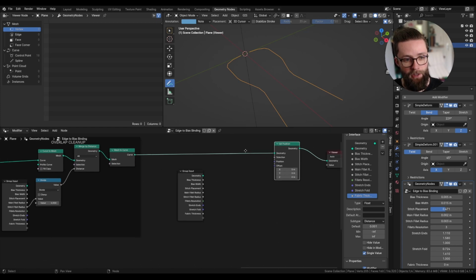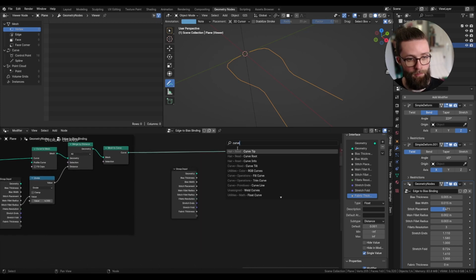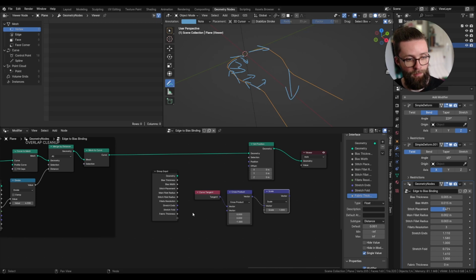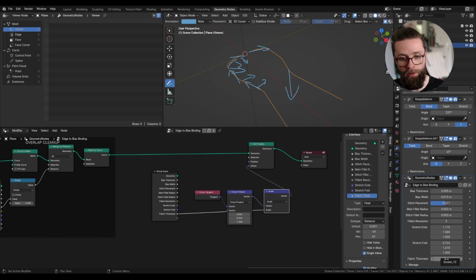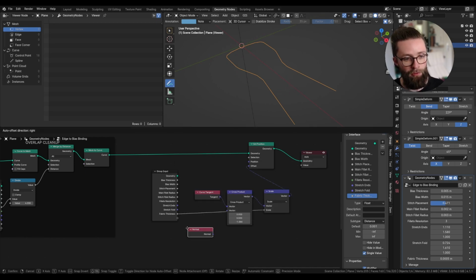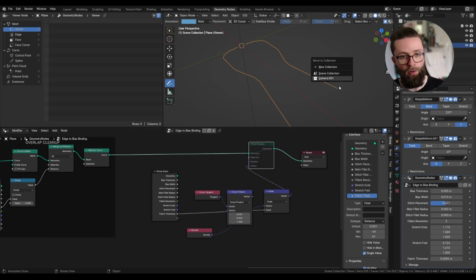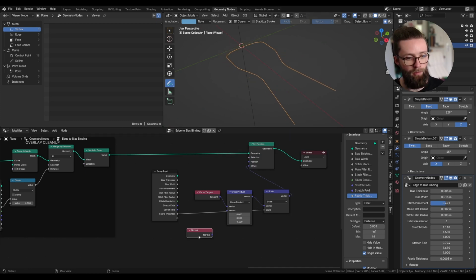Now for the direction of the offset, we can take the curve tangent, which for now is only pointing into those directions all along the curve, and do a cross product with -d, so that we get some vectors that are all pointing inwards. Let's scale this by the fabric thickness and put this into the offset input. And here, if I set the value into the modifier, we should have everything slide inwards. Here we could have used directly the curve normal value, but it isn't always well defined on the endpoints, so the cross product method may work better.